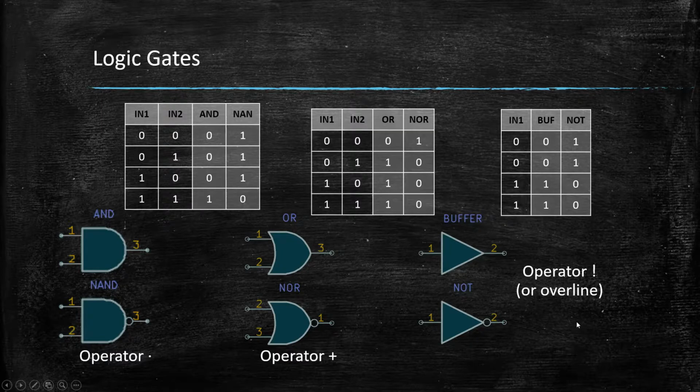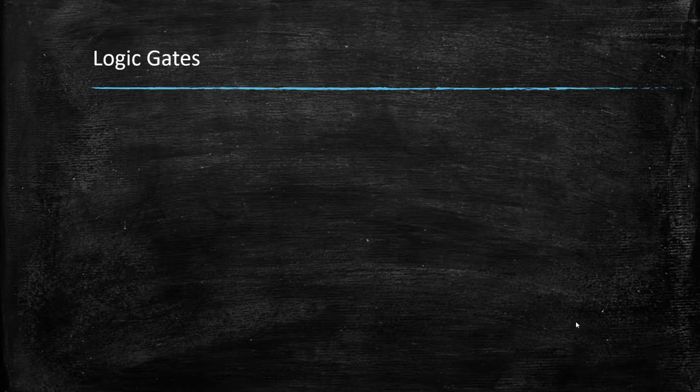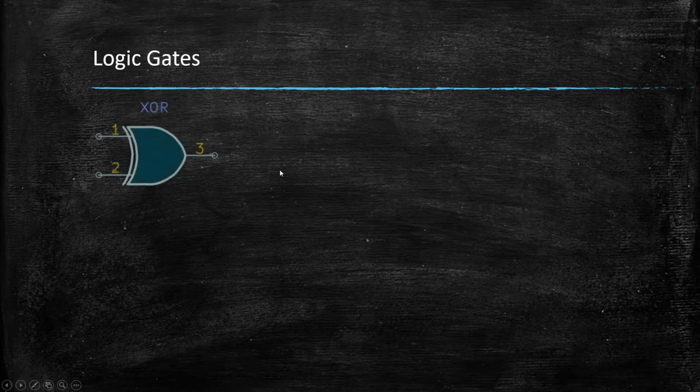Okay, those are the three basic logic gates. However, there is a fourth one which is sometimes considered to be basic. However, it is only basic because the functionality of it is so useful. It is actually made up of multiple single gates, as the implementation of that as a basic gate is, well, I wouldn't say impossible, but I haven't seen any direct implementation that doesn't use ANDs and ORs. So let's just have a look at the exclusive OR gate really quick.